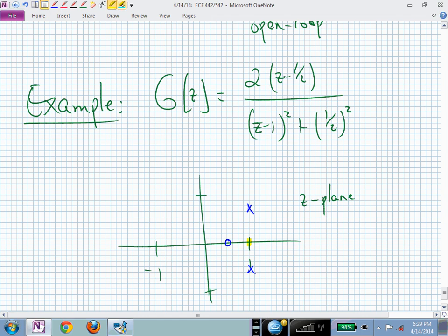What if I come over here to minus 1? And I look to that point, minus 1, from all the points on the real line. There's only one. It's odd. I have to look 180 degrees. And that's consistent with my pole zero excess. So I have 1 zero at infinity for a big enough gain k. Now what happens? How many root locus branches do I have? I have 2 poles, I have 2 branches.